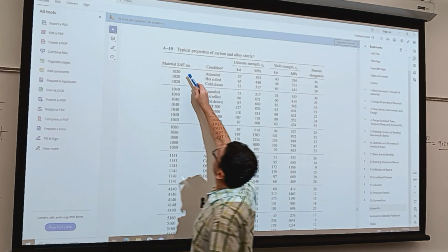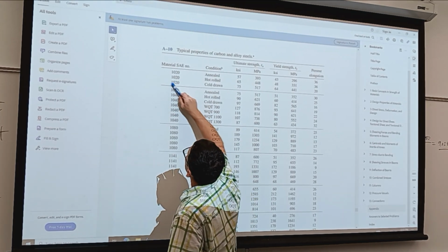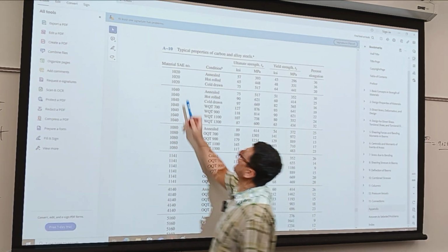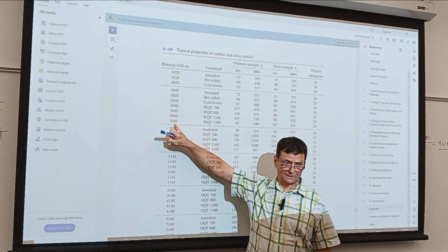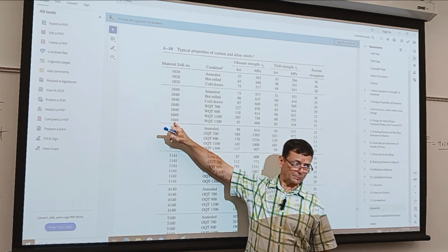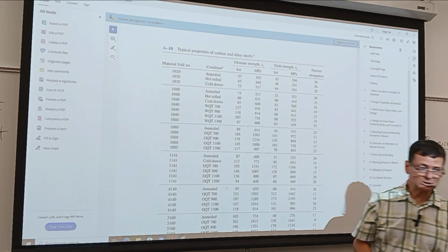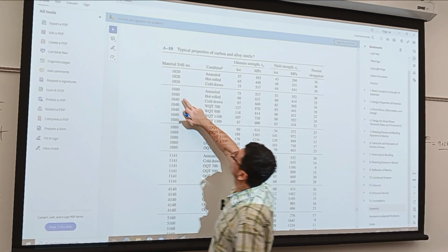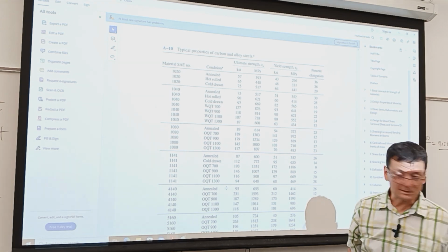So this would be the low carbon steel. This is the medium carbon steel. This is high carbon steel. These weld nicely, but they are softer grades, malleable. These can be heat treated. You can quench and temper them, not to crack. Quenching increases your hardness, but they also become brittle. So you temper a little bit to lose some hardness, but you get more toughness.